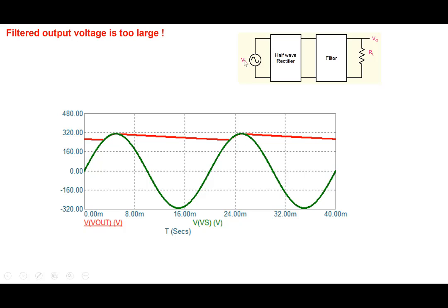So what it says is that we cannot take directly the input voltage that comes in the power outlet and directly half wave rectify and filter it to obtain the value that we want, because that value would be very high.